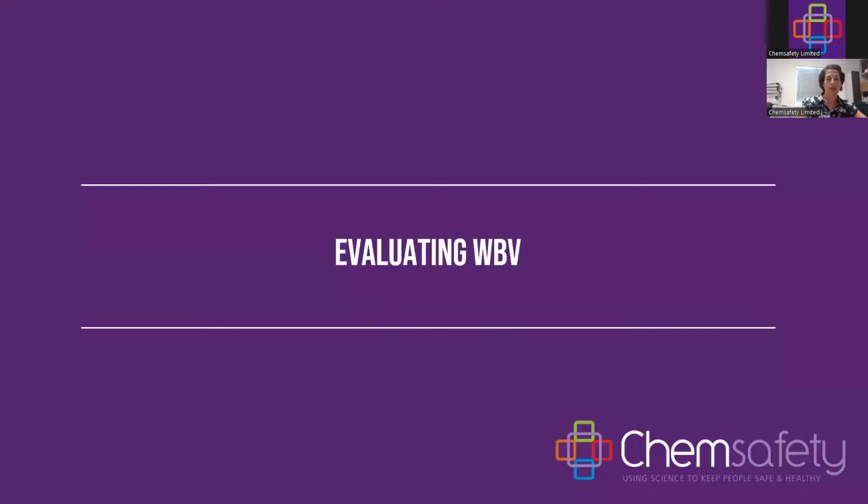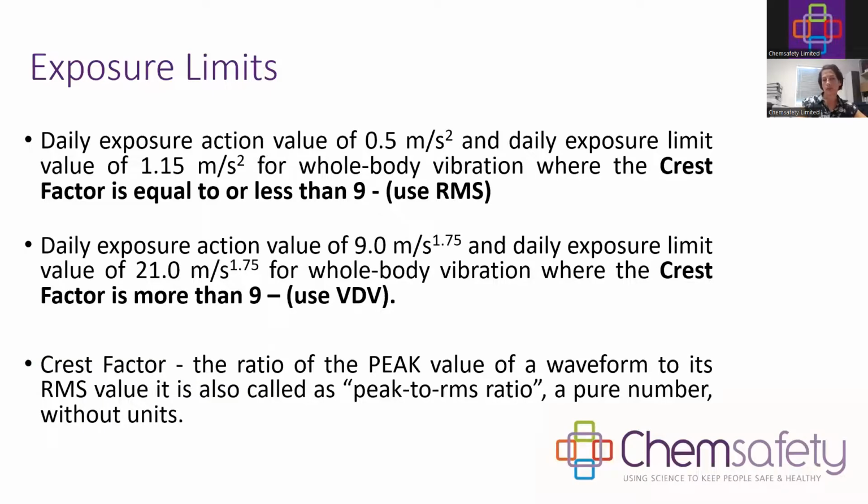So when evaluating whole body vibration, it's a bit more intricate than hand-arm vibration, in the sense that you take into consideration the crest factor. So the crest factor is the ratio of the peak value of a waveform, and it's basically the peak to the RMS ratio. It's a pure number. So what is meant with that is when you're looking at a vibration pattern, you will see different waves. So waves with higher peaks will have a higher crest factor,